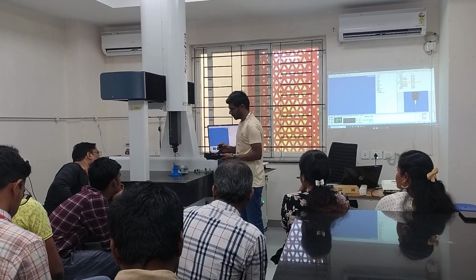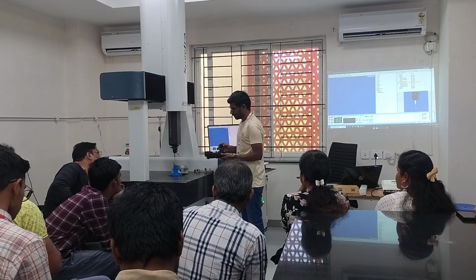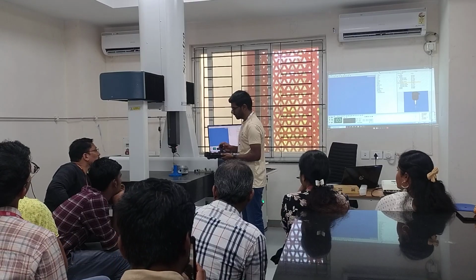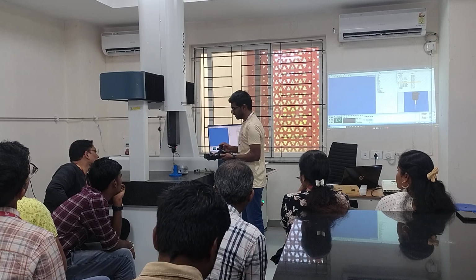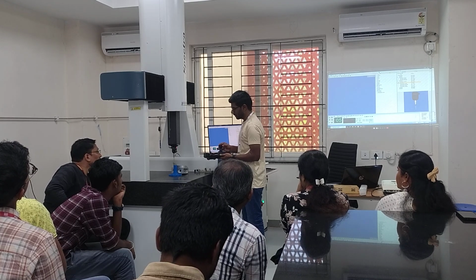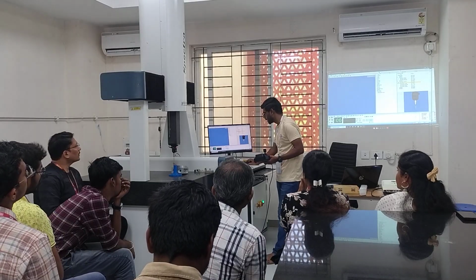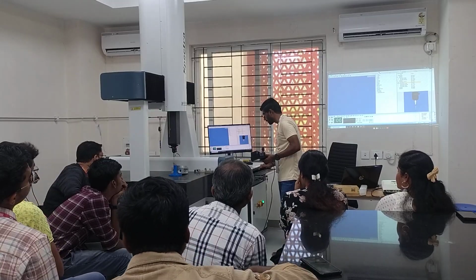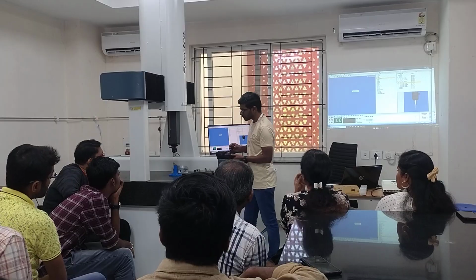One, 2, 3, 4, 5, one more. So 5 points I have taken and I will make it as top plane. I will give the name TOP underscore TLA top plane. Mine is ready. Then I go for the angle plane.